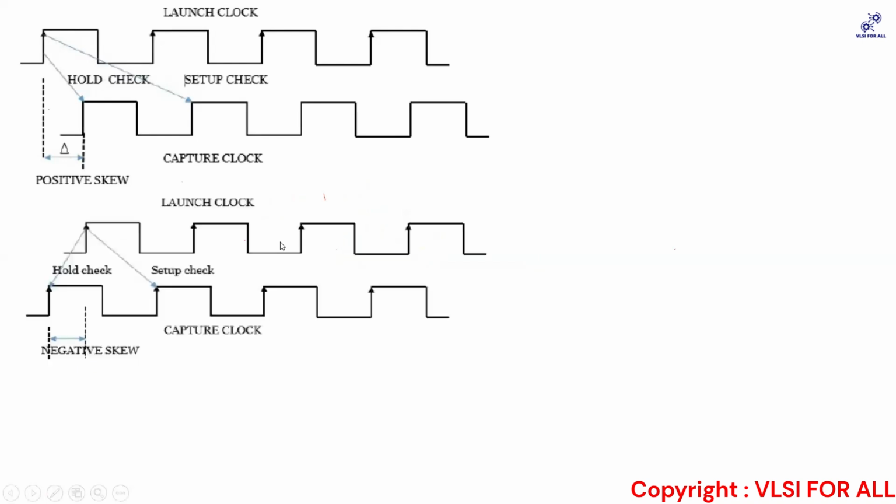Okay, now in the opposite diagram, which clock should come first when I have to denote something as negative skew? Then capture should come first. Correct. Your capture should come first and then your launch should be there.